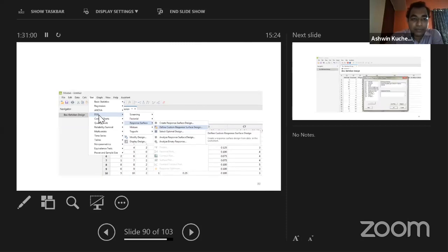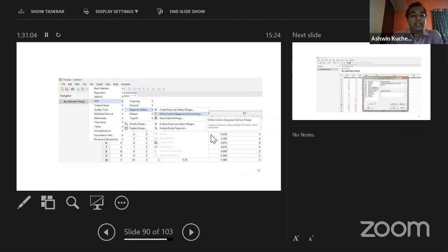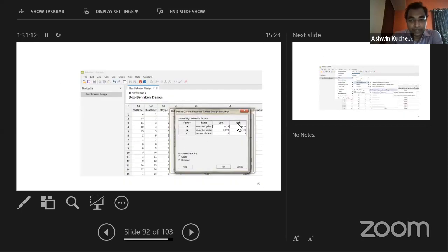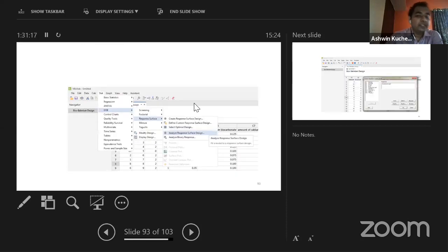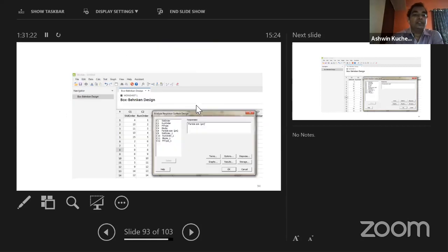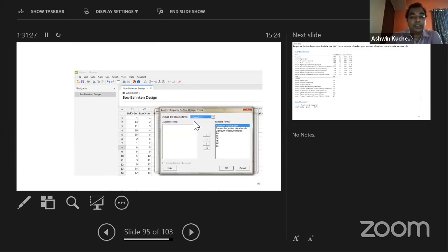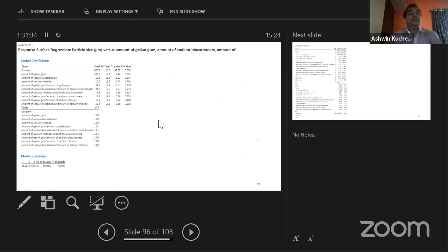So analysis was done like DOE, response surface, defining the response surface, and analyze. Analysis was done with selecting the continuous factors against the response factors. The factors were then mentioned for the low value, high value initially itself. If those were coded, their values were given and the actual values were given. Then analysis was done, selection of the responses against the input variables or controllable variables, selection of the full quadratic term, and plotted and predicted.